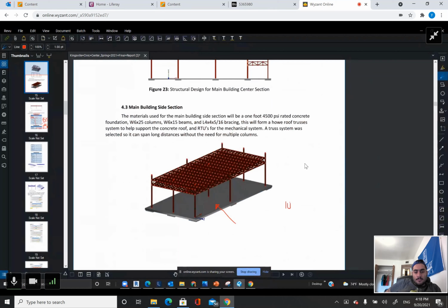So if it's an office building, it's 100 pounds per square foot, or square inch, I forgot. Maybe PSI. If it's a live load for occupants, that's the difference here between dead load and live load. But the way to do it is to lay out the structural grid, right? You might have to make some assumptions on these, but they should be based on the loads. And you would analyze the worst case scenario for the columns, and maybe you would just use that column everywhere.